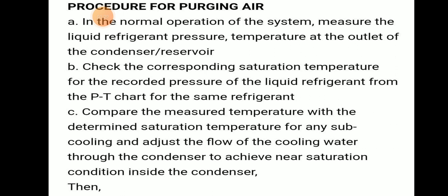We will compare the measured temperature with the determined saturation temperature for any subcooling, and adjust the flow of cooling water through the condenser to achieve near saturation condition inside the condenser.